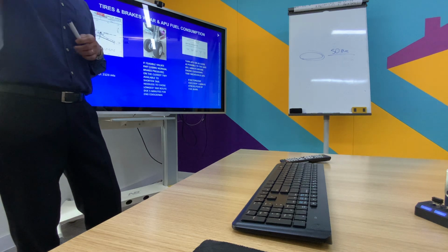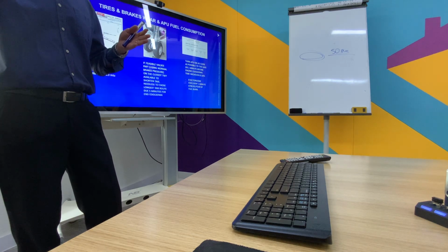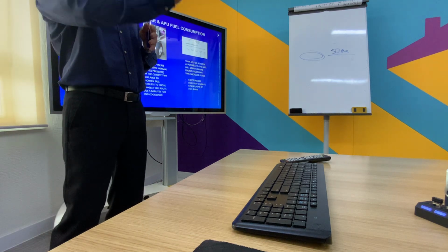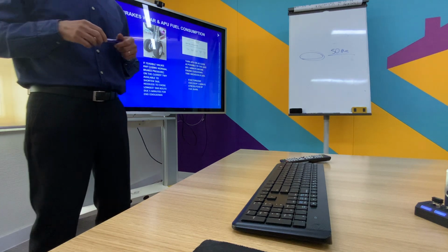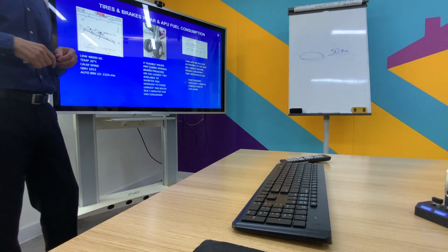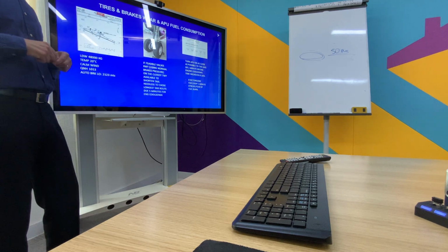Okay. On the E1, as we don't have this limitation for 5 minutes, when I'm getting close to the gate, before entering the gate, turn on the APU. It takes around 50 seconds. Suggestion, just a suggestion.